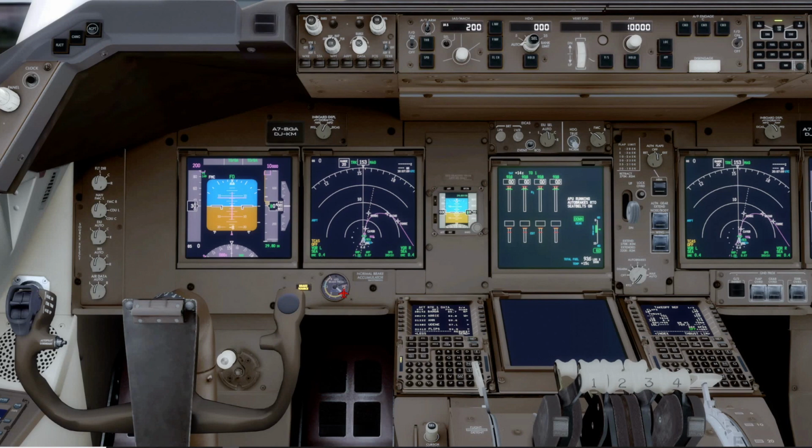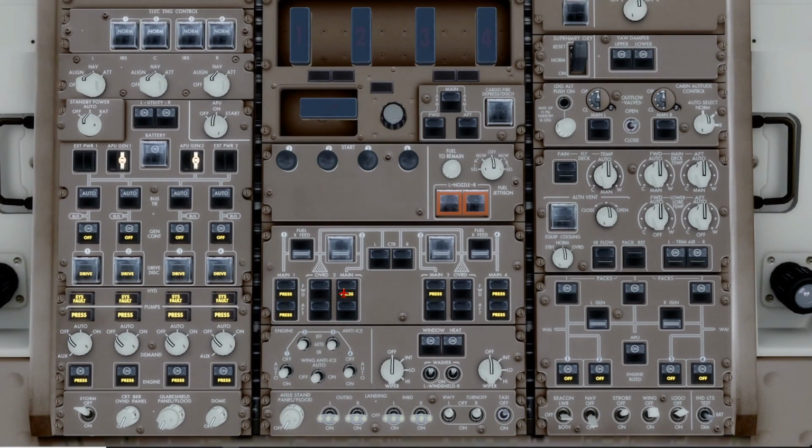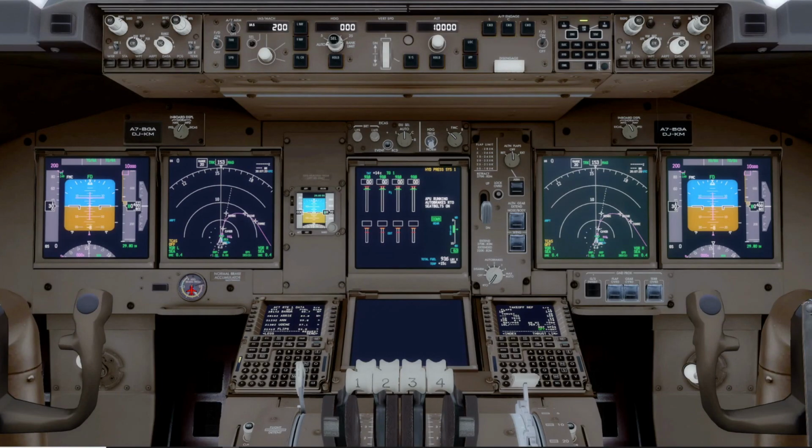It's down to pre-charge. We could, if we wanted, go up to the hydraulic panel, go to aux. That'll pressurize the accumulator. You don't have to get ground clearance to do that. You're not pressurizing the whole hydraulic system, just the aux pump, which will go to the brakes, and set that. So if you ever need to pump it up, if you do that, the light goes out, the brake source light goes out when you're doing that. And we'll pump up the accumulator, and then we'll go back to off on the selector. And then the brake source light will come back on because there's no active brake source once you turn that off. The accumulator, of course, will hold the pressure to the brakes at that point.